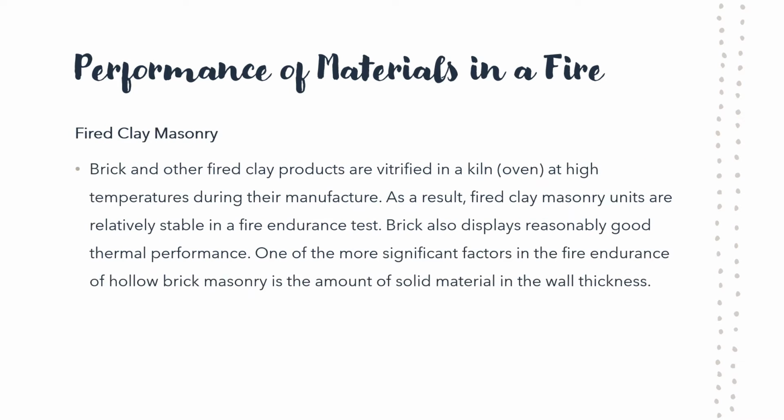Fired clay masonry or brick and other fired clay products are vitrified in a kiln or oven at high temperatures during their manufacture. As a result, fired clay masonry units are relatively stable in a fire endurance test. Brick also displays reasonably good thermal performance. One of the more significant factors in the fire endurance of hollow brick masonry is the amount of solid material in the wall thickness.